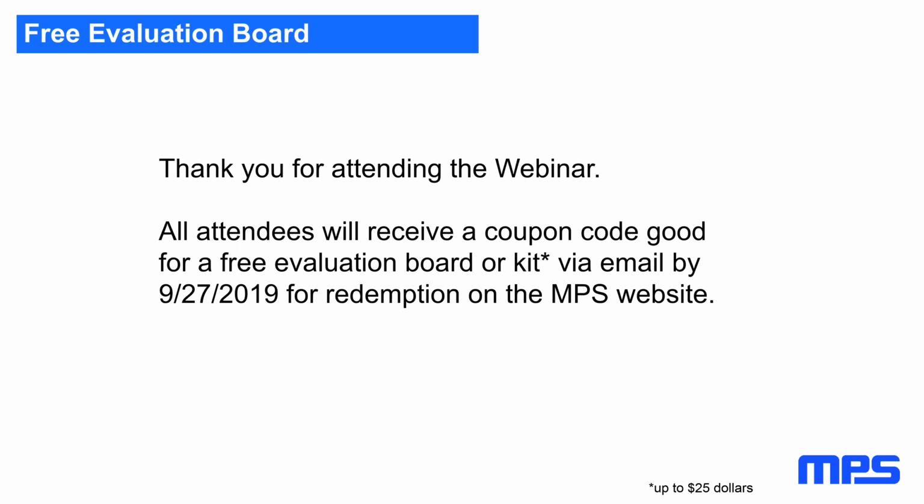Above 30 megahertz, you need higher modulation depth or a higher modulation span if you want it anyway, so I would go higher if you can. Typically, plus or minus 3 kilohertz or plus or minus 5 kilohertz doesn't help much. At 400 kilohertz, go plus or minus 40 kilohertz, or something in the range of 10, 20, 30% of the switching frequency, and not lower, unless you have a very special requirement.